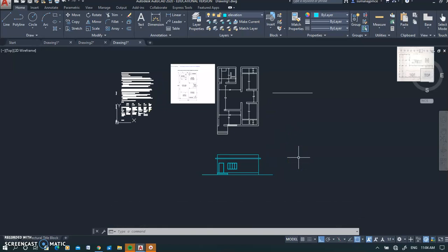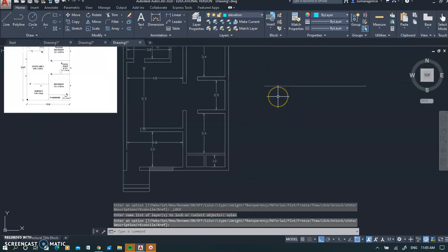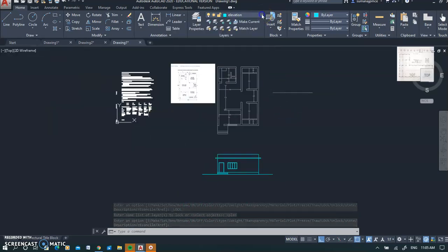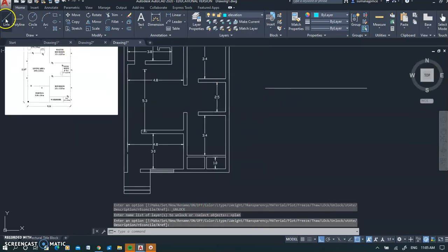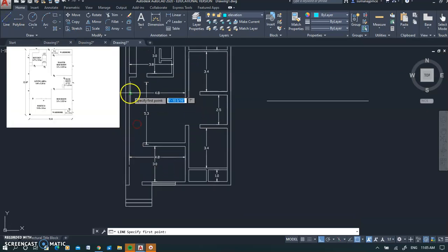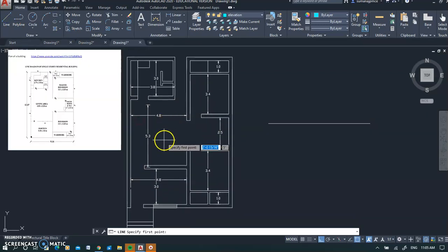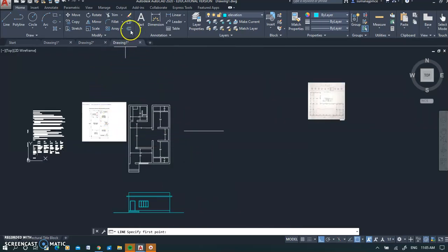As I showed you when you handed the drawing, we have got the elevation and plan. Now we will see how we can draw a section. Now I will draw the section again in the elevation layer. So what I will do is same thing. I will repeat. I will lock the plan layer and I will go to the section. But before that, let me unlock the layer and let me draw a section line, let's say, which shows a good number of details. That is where you should draw a section line.